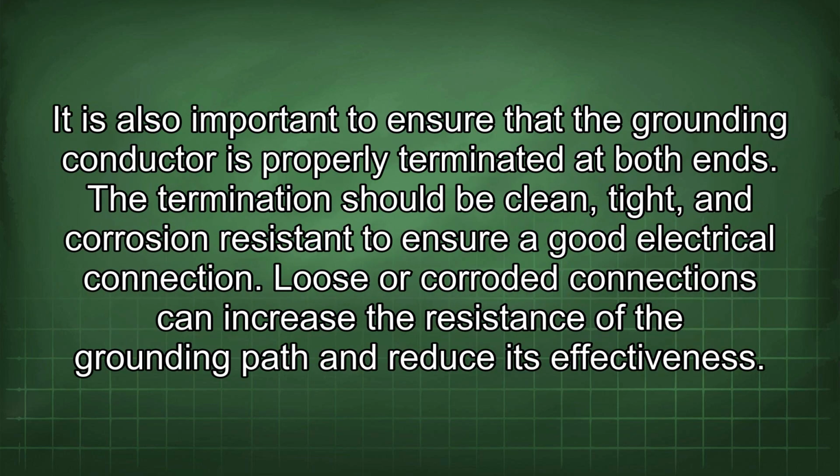It is also important to ensure that the grounding conductor is properly terminated at both ends. The termination should be clean, tight, and corrosion-resistant to ensure a good electrical connection. Loose or corroded connections can increase the resistance of the grounding path and reduce its effectiveness.